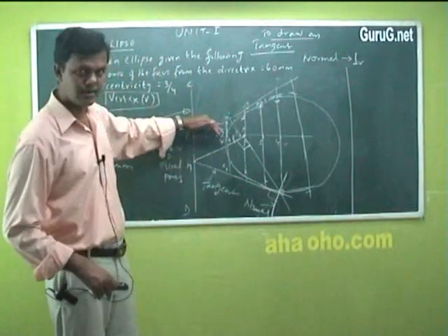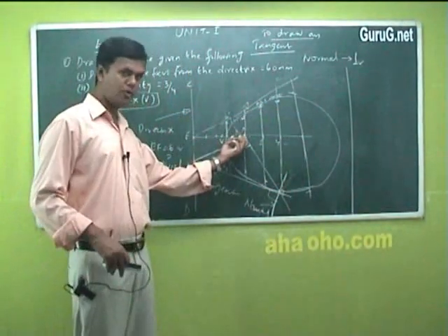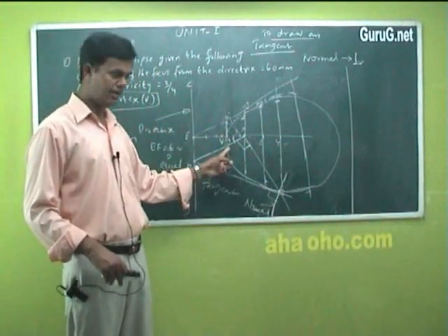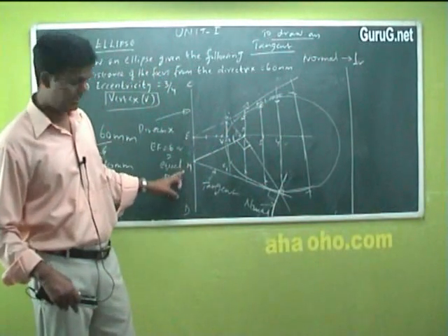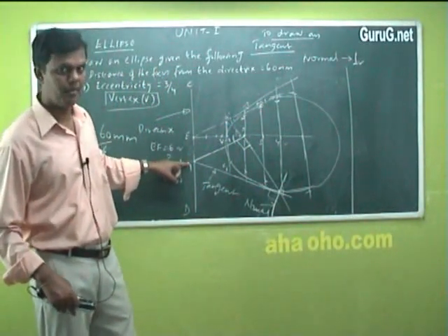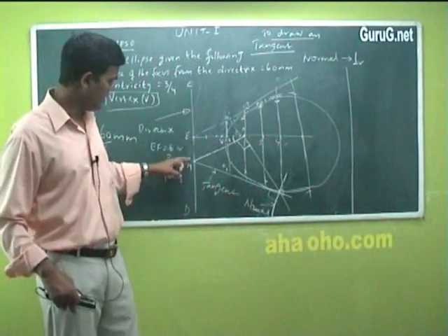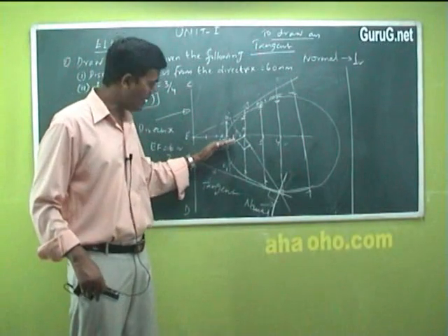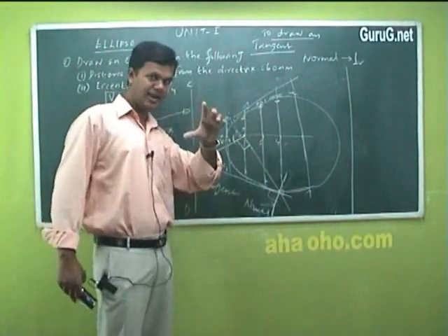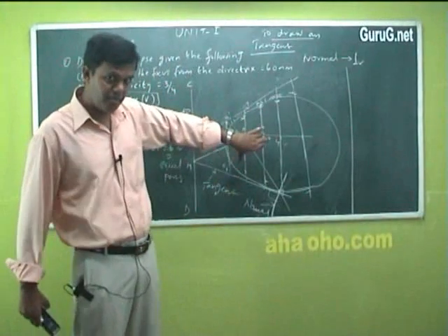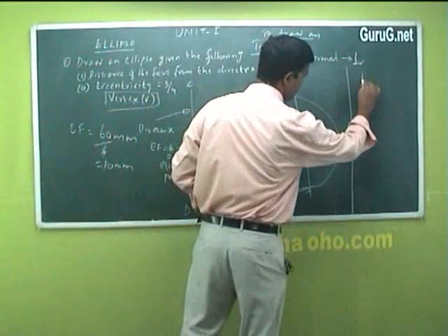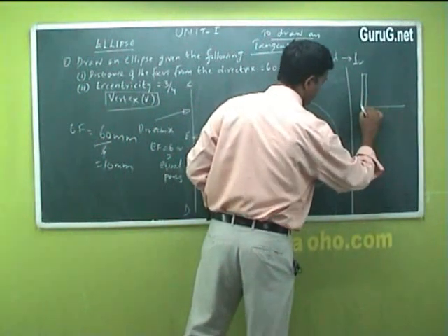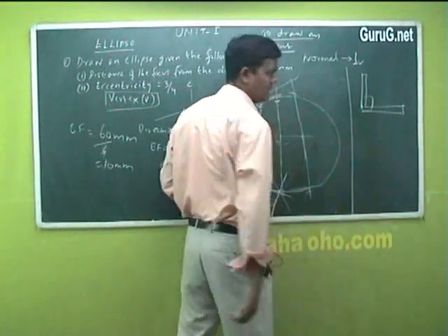After making this curve, from the focus point you should take a line at a 45-degree angle which touches the directrix at point M, or whatever distance you keep. From that point you should draw a line exactly perpendicular to this line, because when you fix the drafter, the opposite scale will always make a 90-degree angle.